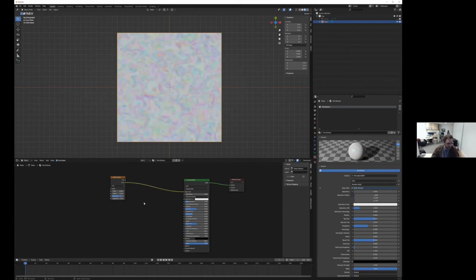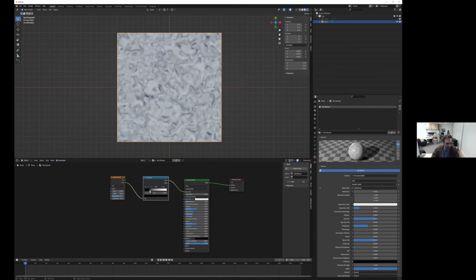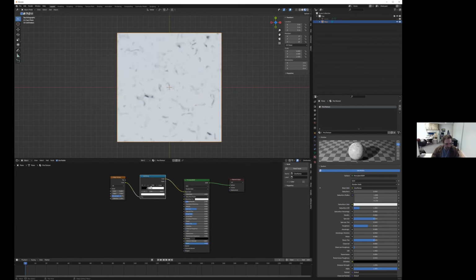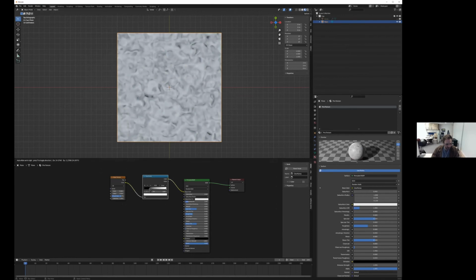So this I wanted to show you guys because I think this could be very interesting in terms of creativity and whatnot. So if I go ahead and I'm going to add one more thing, and it's going to be called a color ramp. So I can even search for it, and I find this color ramp. Color ramp is one of probably the most frequent nodes I use. It is very popular. It allows you to do some really cool things. And so this is one example of putting the noise texture into the color ramp, and then that will establish your base color. And so I can use these bars to kind of change the brightness and the contrast of my texture that's being displayed.